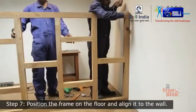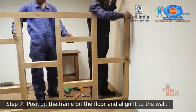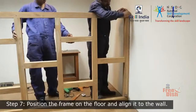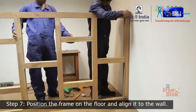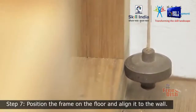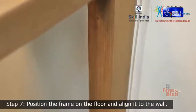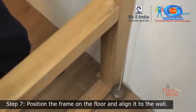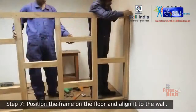To do this, you will need a plumb bob. Hold the plumb bob from the top edge of the frame and allow it to hang at the bottom of the frame. Slow the plumb bob from swinging with your hand. Once it is still, the plumb bob should touch the frame slightly. Determine the distance from the string to the frame sides at both the top and the bottom. If required, adjust the frame until both are equal.